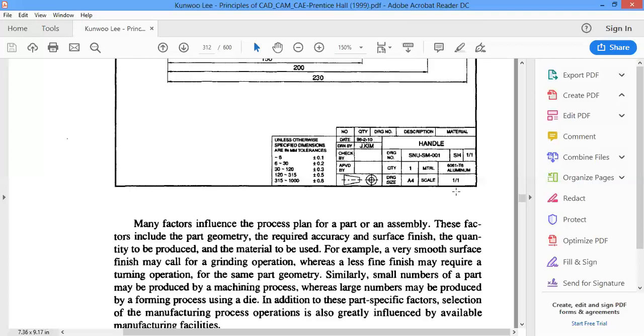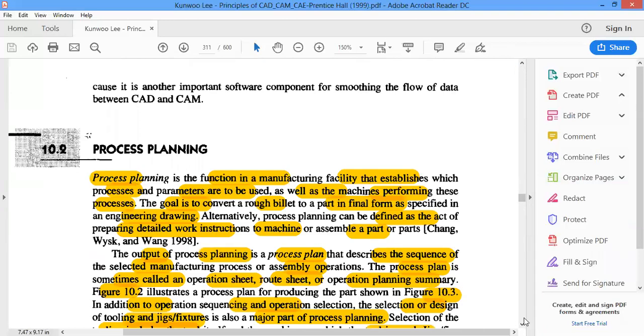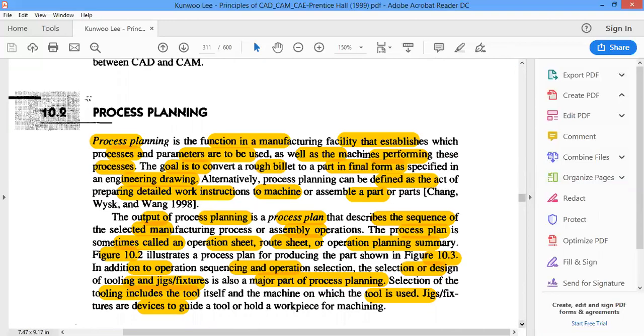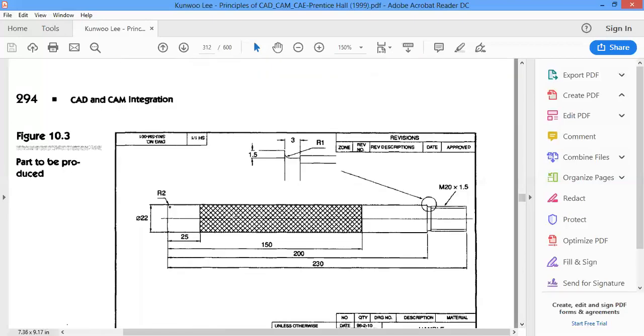And similarly, the quality inspection people will also receive the drawing sheets, and in quality inspection, they check which are the dimensions, whether the knurling has taken place properly or not, right? Very critical dimensions and other features also they have to check, and they have to make a record of that, and the part is going to be passed or not.